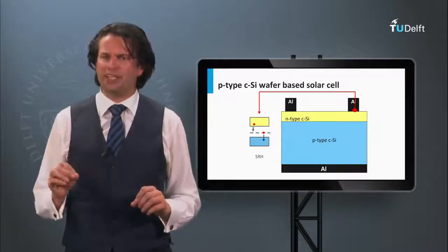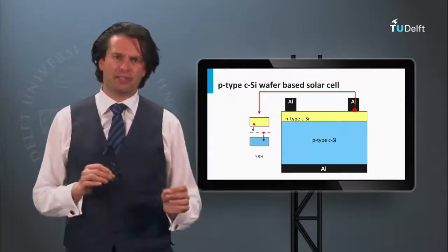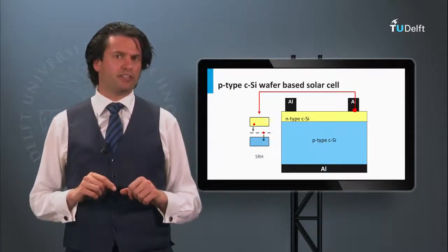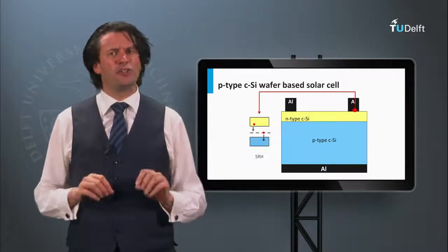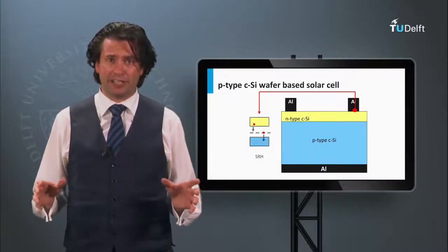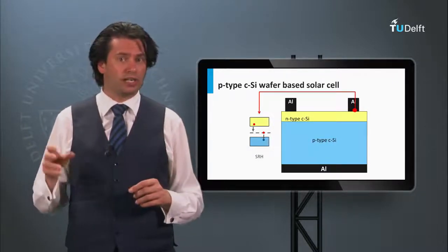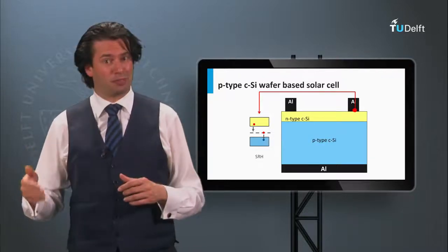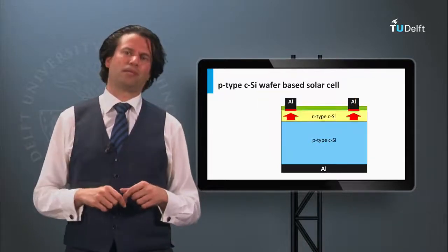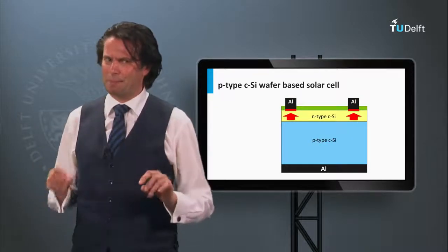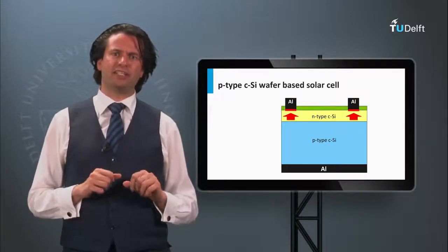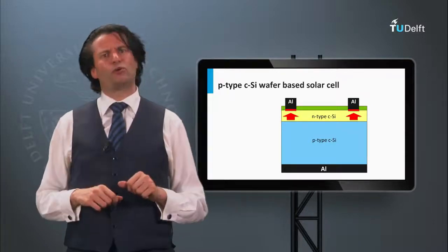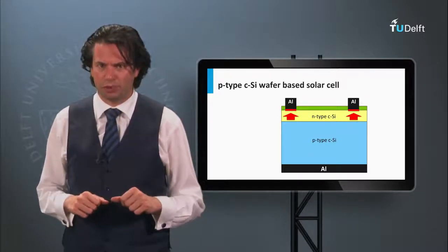Now we look in more detail at the metal-emitter interface. A problem at this metal-emitter interface is that we cannot use an insulating passivation layer like silicon oxide or silicon nitride anymore, as we need electrons to conduct from the semiconductor to the metal. This means that the metal-semiconductor interface has more defects and therefore an unwelcome high interface recombination velocity.